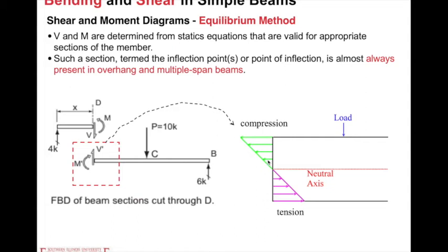If we look at the very first close piece, this is compression stress, and this is tension stress. You can notice that the magnitudes of these two are the same, but in opposite directions. That means these two internal stresses can form a force couple, which has only a pure moment.